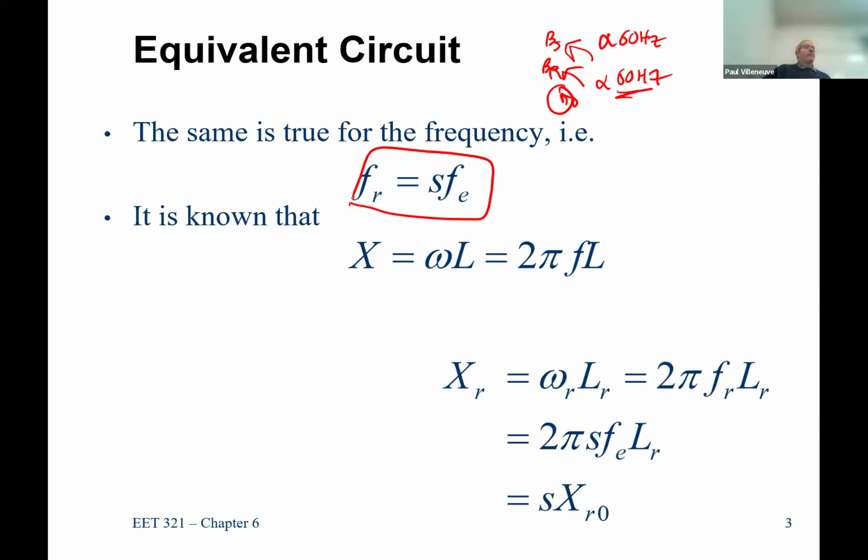All right. Back before we had semiconductor devices, there used to be things called rotary converters. A rotary converter was essentially a variable frequency drive that you could get different frequencies out of. You would just monkey with the speed of operation of the rotor. And if you had a way of pulling off the AC out of the center, you've got a variable frequency drive. Very expensive one, right? Not very efficient, but that works really well.